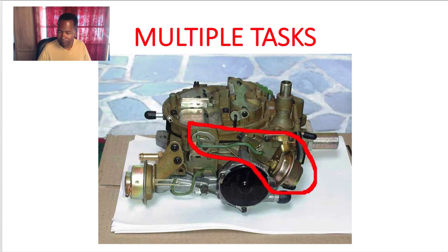That's the choke pull-off. You can see the adjustment right here. How it adjusts, you see this little slot here. You see this little lever right here? That lever connects to this choke spring inside here. That's why it's closed by that lever. By this lever right here, it connects to this choke spring.